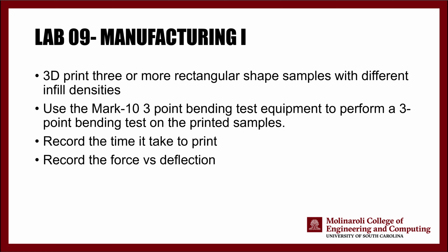So essentially, you 3D print a sample, you measure the time it takes to print, and then you measure the deflection versus a specific force. Then you can create curve fits for your 3D printed material, and you can give us a functionality. Essentially, you can give us how much time it takes versus the infill density, and the structural integrity versus the infill density.